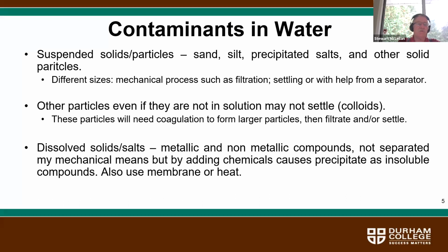You also have the dissolved solids and salts, metallic and non-metallic compounds not separated by mechanical means, but by adding chemicals, causing precipitates as insoluble compounds. Okay, and that comes back to the last point, where many industrial facilities have dissolved solids in their wastewater, and they precipitate it.